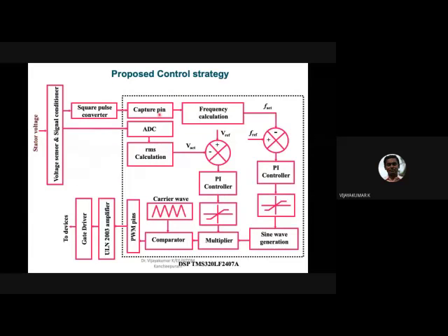If you have DSP processors or FPGA controllers, then we can calculate or estimate the actual voltage magnitude and frequency from a single sine wave. A single sine wave means you can take the stator voltage instantaneous waveform, and from that, by using digital signal processing, you can estimate the voltage magnitude and frequency. For the voltage reference and frequency reference, if it's three-phase, you have to make it 440 volt and the frequency 50 hertz. You can give that as a reference to your control loops.